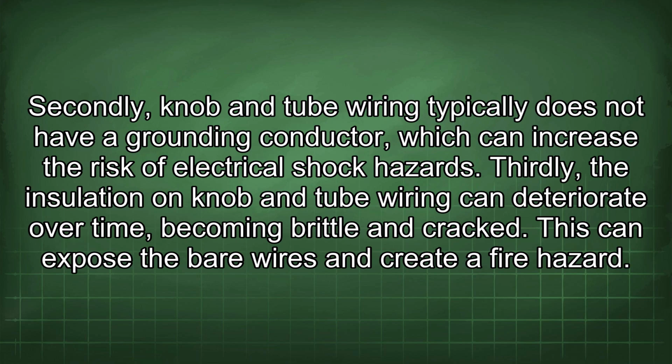Secondly, knob and tube wiring typically does not have a grounding conductor, which can increase the risk of electrical shock hazards. Thirdly, the insulation on knob and tube wiring can deteriorate over time, becoming brittle and cracked. This can expose the bare wires and create a fire hazard.